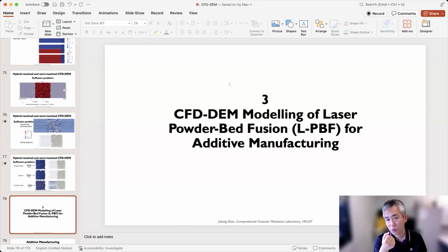It can be addressed, but it really depends on what benefit you would prefer, computational efficiency or accuracy, or you want to have a balance of it. Okay, in a sense, DEM indeed can help you capture whatever of these things, and you can specify a more advanced model to describe how progressive damage in a bond develops, right? And you can use certain models to describe the plasticity, viscosity, and viscoplasticity to address the rate effect here.